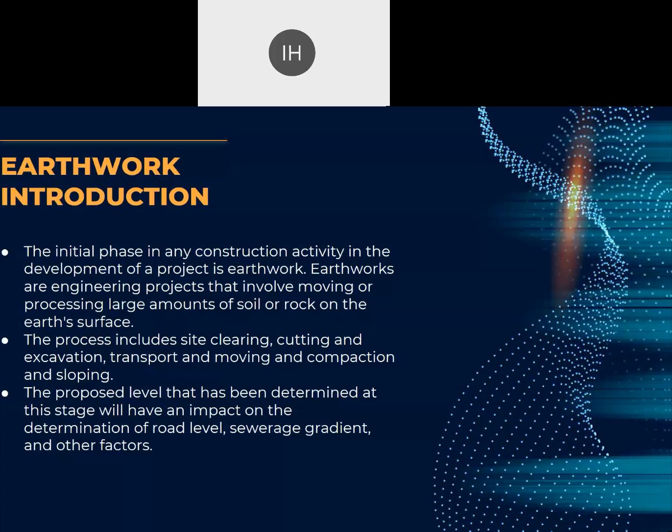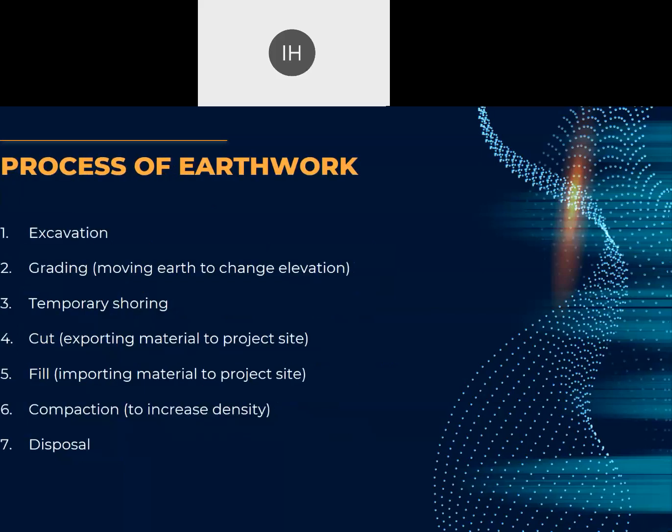The proposed level determined at this stage will have an impact on the determination of road level, sewerage, gradient, and other factors. The process of earthwork includes excavation, grading, temporary shoring, cut and fill, compaction, and lastly disposal.